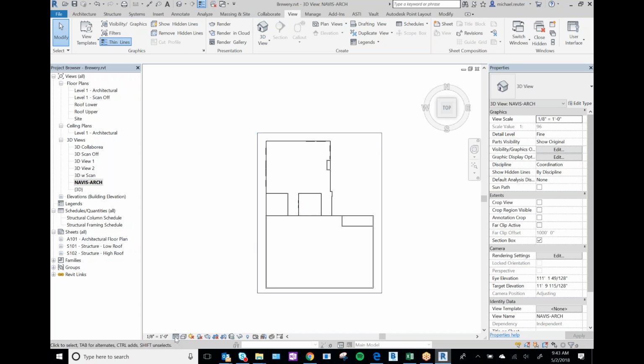So if you're working with a plumbing file, or really, it's just best practice to do fine level of detail. It would probably be okay if we just did medium for architectural or structural or even ductwork, but for sprinkler, for anything small, anything that's like, let's say 3 inches or smaller, we would want to have fine detail on. So I'm just going to keep it on here as reminders to show you how I did it. Okay, so we've got our architectural file taken care of.